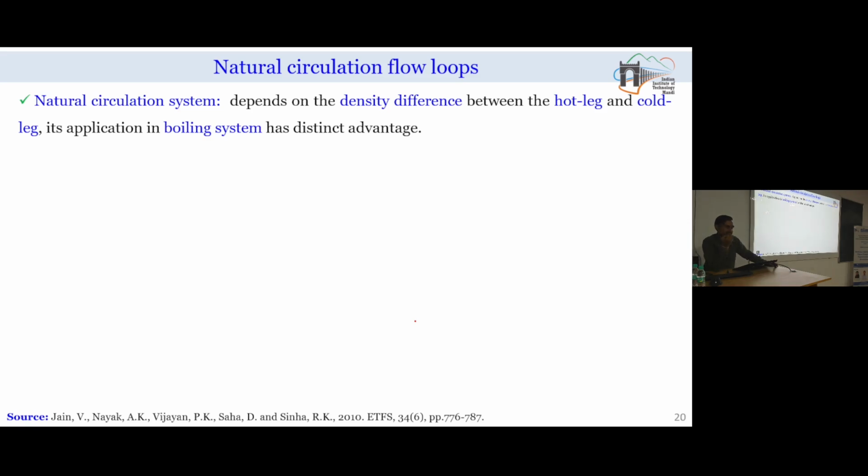We know that in the nuclear industry it is very difficult to control the rate at which heat is added to the working fluid. And if there is any accidental situation, say your pump has stopped working, in that scenario what will happen? Your coolant will not be circulated. If coolant is not being circulated, you will experience loss of coolant, and suddenly whatever water or any type of coolant is there will immediately get converted into vapor, and once it has converted into vapor, dry out will happen, and this will lead to overheating of the system, and there can even be meltdown or other types of failure.